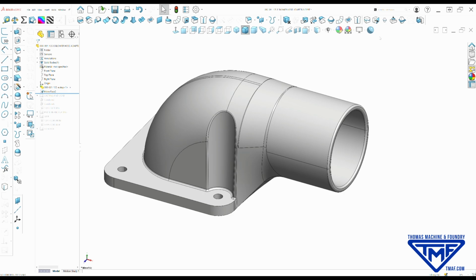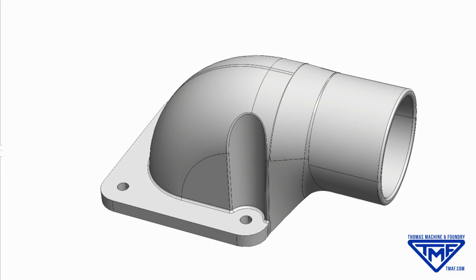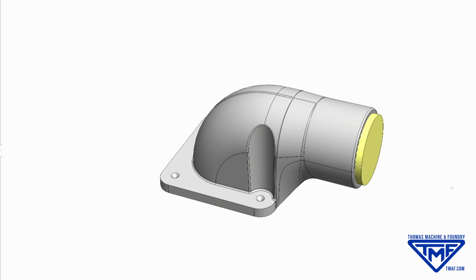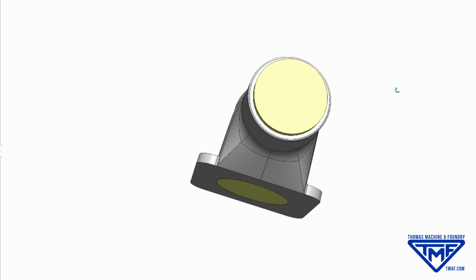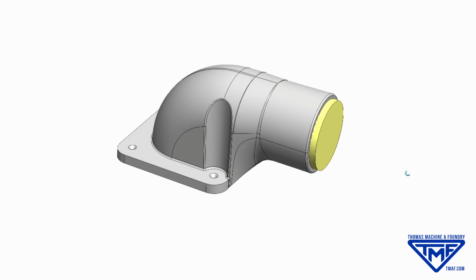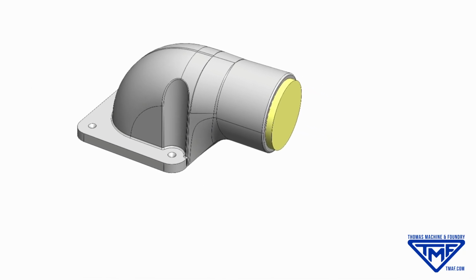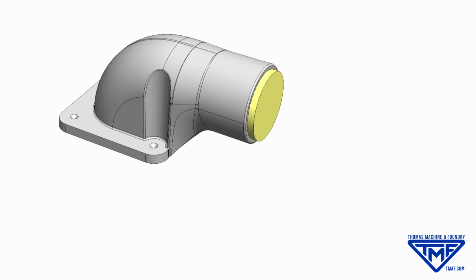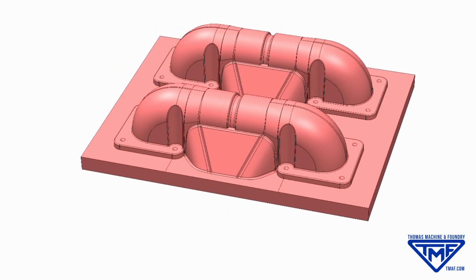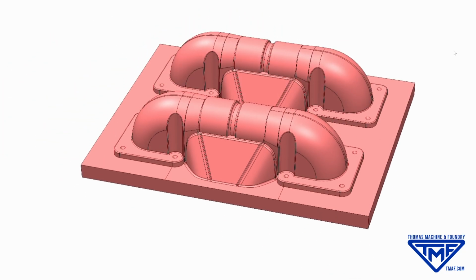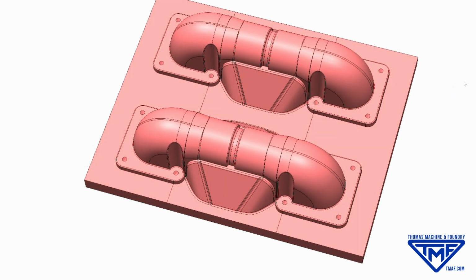But the finished casting model is only the beginning. Now we begin building the pattern. The individual part geometry is prepared, draft is added, machining allowances are considered, shrink factor is applied, and the features needed for the molding processes are incorporated into the design. Once one cavity is complete, the process can begin to scale. This single part becomes multiple cavities arranged on a pattern board. In this case, a 4-cavity pattern. 4 identical copies of the part integrated into one pattern board.